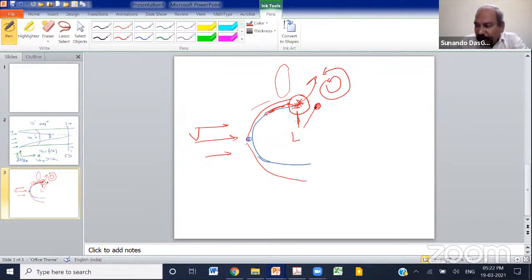Therefore, the velocity of the fluid particle in turbulent flow, which was higher to begin with, will become zero at a point later than that of the laminar flow. And this is the reason why the fluid is going to come to rest over here in turbulent flow, and then from this point, it's going to detach from the surface.